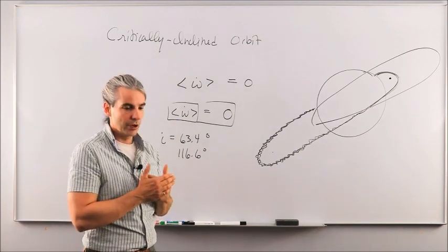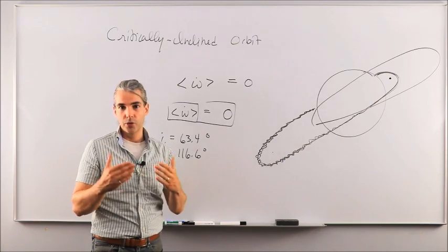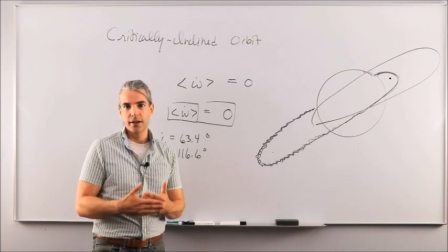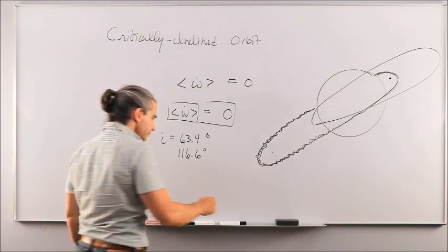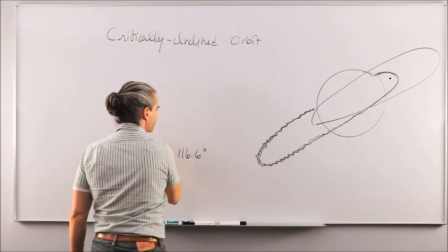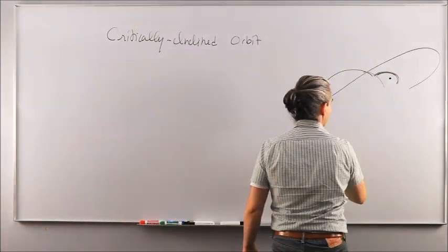Always go back to expressing the vectorial equation of your perturbing acceleration, which could be whatever, inside the orbital reference frame, extract Fr, F theta, and Fz out of it, and just follow the process. Okay? So again, this concludes the discussion on J2. Now what I want to do next is look at drag.